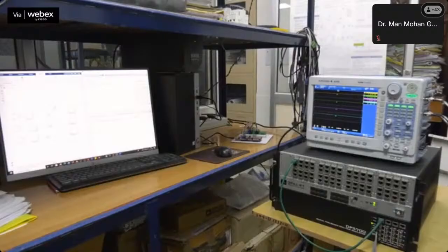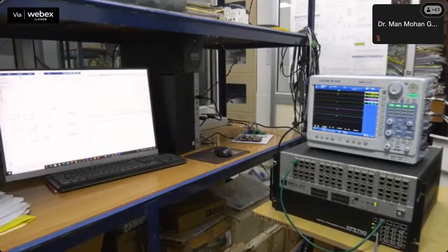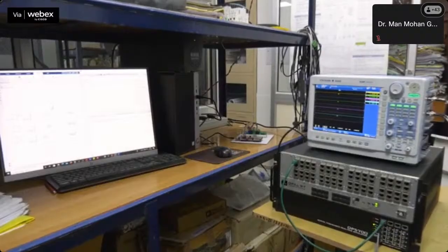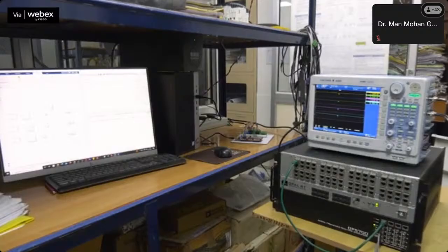Now, if you focus on discharging operation, the individual battery currents are presented in the DSO at the first 3 channels and SOC values in the next 3 channels and power demand PD in the 7th channel respectively.